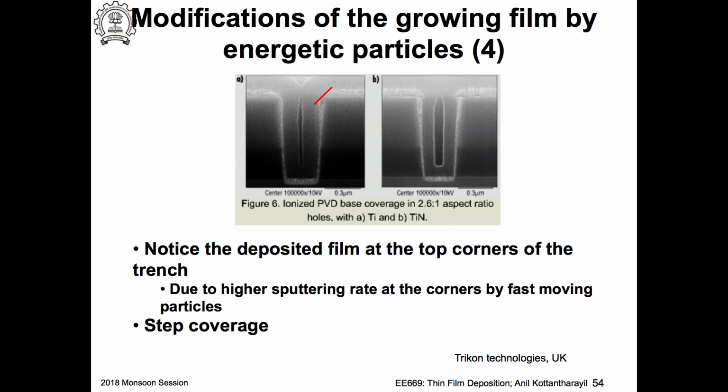It just dislodges from the, okay. So on this side, it is easier to remove material. So sputter rates at these corners would be usually higher than at the top. As a consequence, you can get this, and it is important to keep the mouth of this open. Otherwise, you may have an overhang, and this would then lead to poor step coverage. So you keep the conditions so that there is the difference that you see between these two.